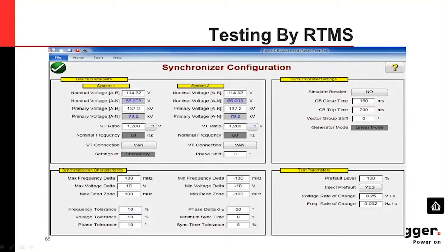We just put the system voltage, which is system 1 and system 2 details, and then we come here and put the frequency. We have the frequency, delta voltage, the voltage difference, and also the phase difference over here. So that's what we need: the frequency, voltage difference, and phase difference. From here, we can test only these 3 quantities.